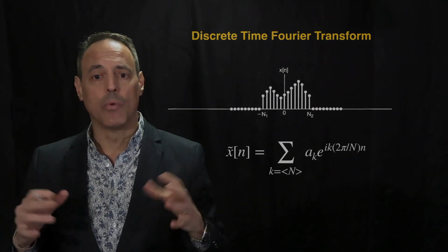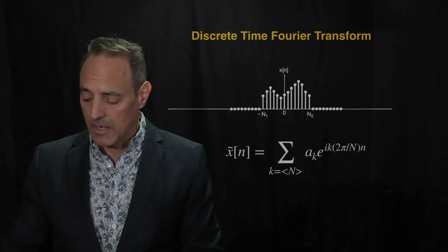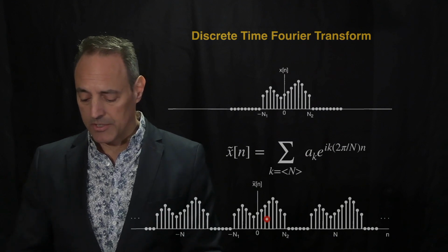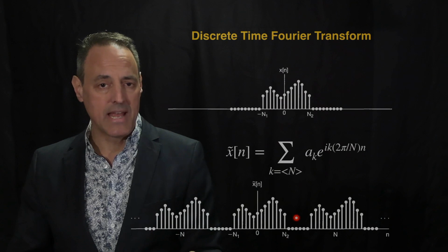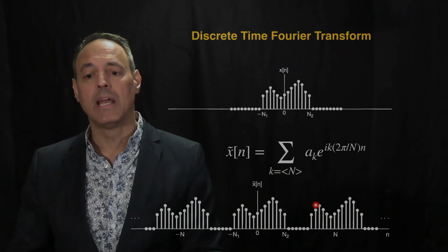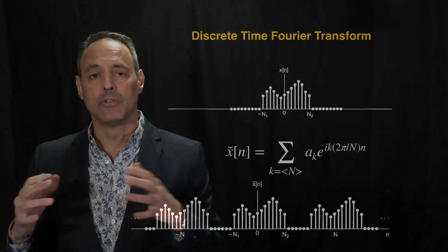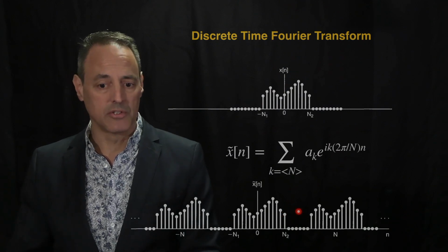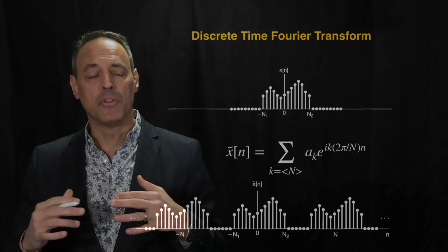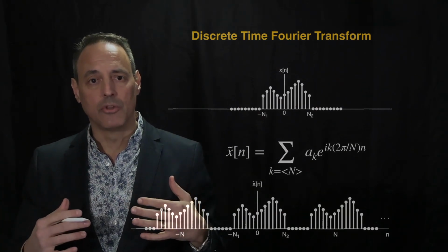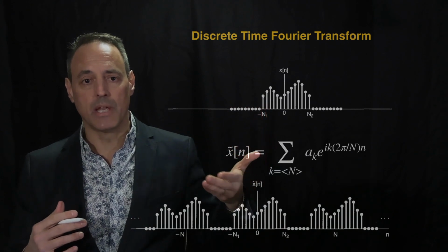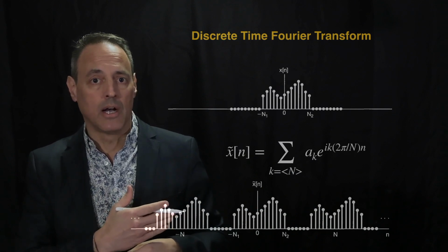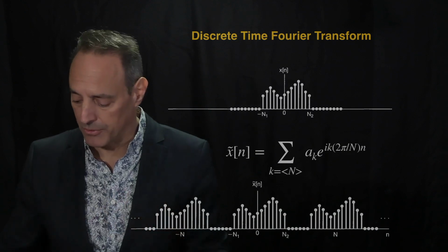So what's going to happen is when I represent this discrete time signal in any actual application, it's going to be a repeating pattern. So here it is. Here is your basic signal with some n, which is your period that you've chosen for this, and this pattern repeats itself in time, so it's periodic with a period of n points. And of course, this n has to include negative n1 to n2 if I want to capture the signal correctly. But remember, this is a representation or an approximation to the real signal, which is here. And now once we go to the Fourier domain, I have this periodic signal that you're seeing here because I've committed to using these cosines and sines, which are these complex exponentials.